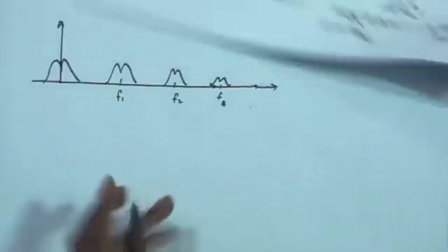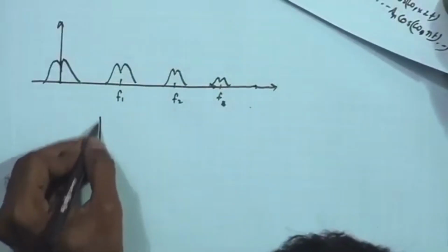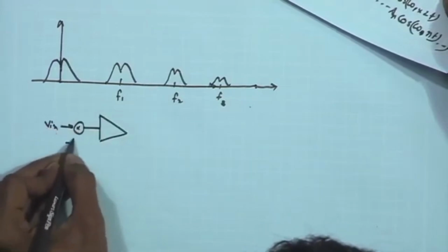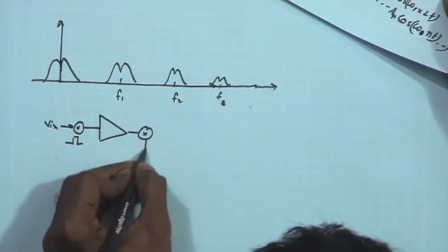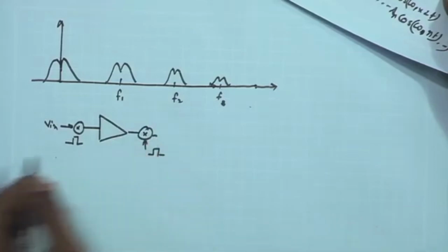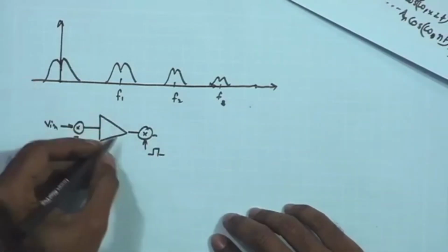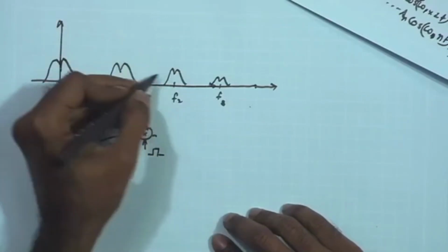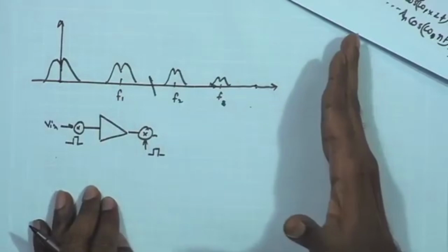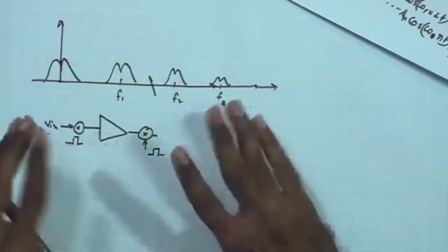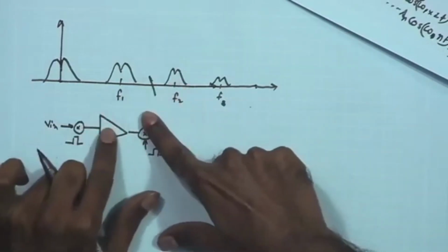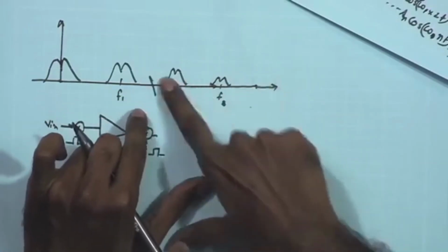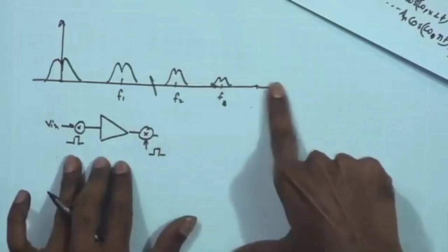and then after the amplifier we can once again go back with the reverse process. We can once again multiply it by the same frequency, and if the amplifier is having its bandwidth which is limited, it will definitely reject the higher frequency harmonics coming into picture. We know that ultimately our amplifier is going to have some band limitation, and we make sure that it is sufficiently lower than f2. So, we can ignore the higher harmonics coming into picture and assume that they will be diminished.